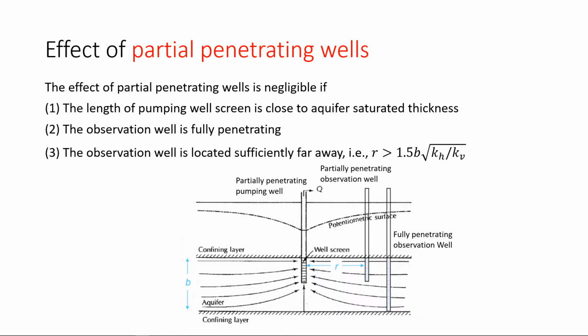Remember, with Theis's method, for example, if you want to use it, it is valid if your pumping well and your observation well are fully penetrating. But in certain cases, that might not be the case.